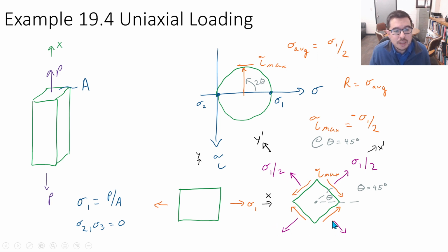And if we've gone the positive 45 degrees or the positive 90 degrees on the circle, this x out here is now really up here. So this is the sigma x prime, which is what you see there, x prime direction, and the y prime direction is over here. So you see how tau, now in this corner where you have x prime, y prime, if I drew this one first, it's going the opposite direction of what we usually use for the positive convention.